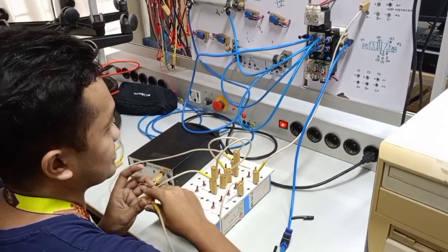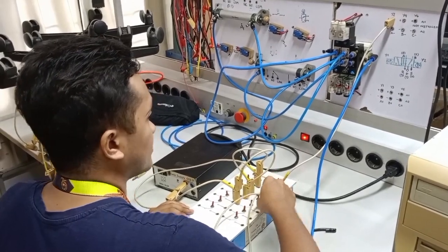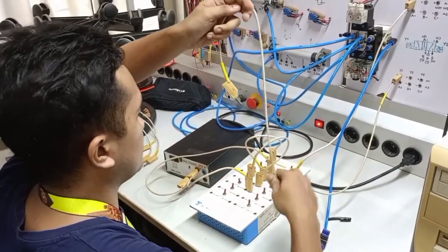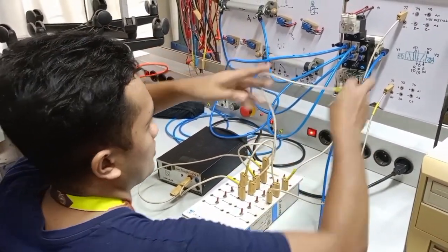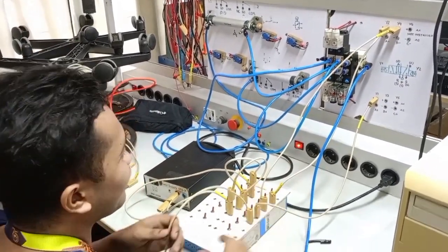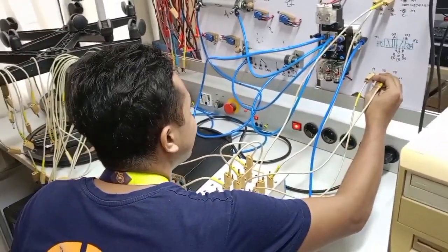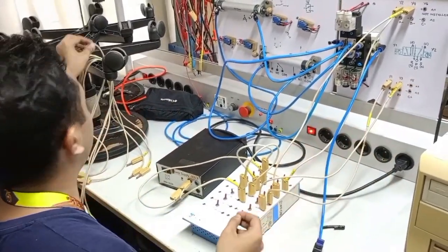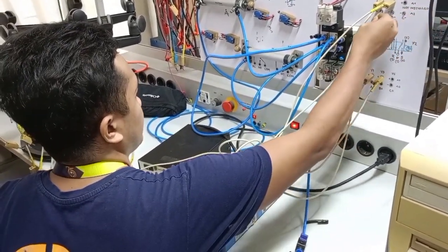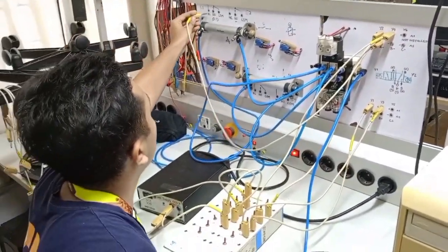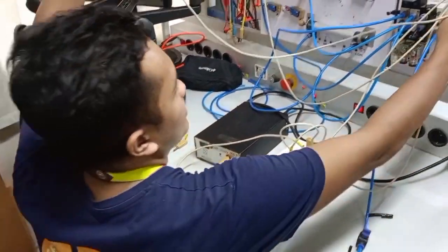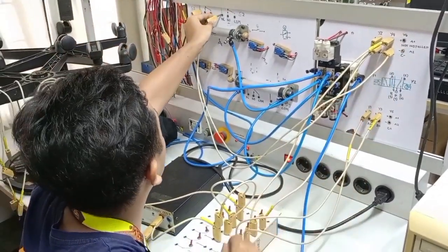So now I connect it. The first switch, I connect it to the Y2 solenoid in the upper part, and the Y1 solenoid in the lower part, lower left. So likewise, switch 3 and switch 4. Then A plus, B plus, A minus, and B minus will be connected to our cylinder.